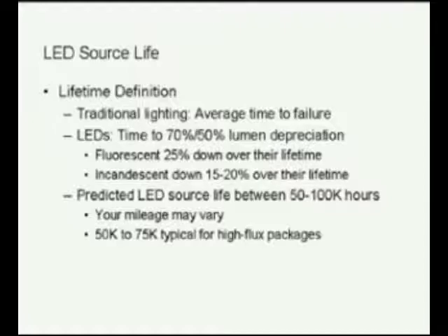With LEDs, you don't have a filament, so the mechanism for failure is much different. In fact, the mechanism takes a very long time. It's termed lumen depreciation, and that is the light drops in output over a very long period of time. So the difficulty is, how do you define failure if it's still emitting light? Well, the industry and customers within the industry have come to a consensus that if your light output is down around 30% from initial light output, that could be defined as your lifetime.